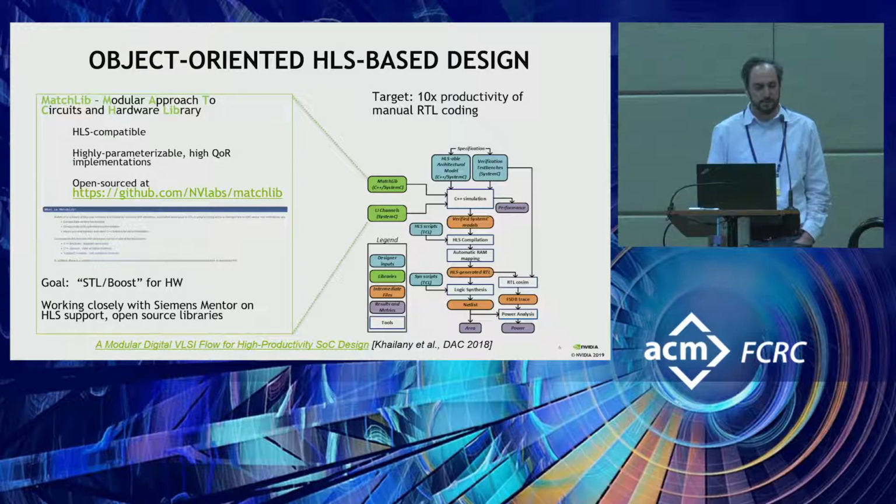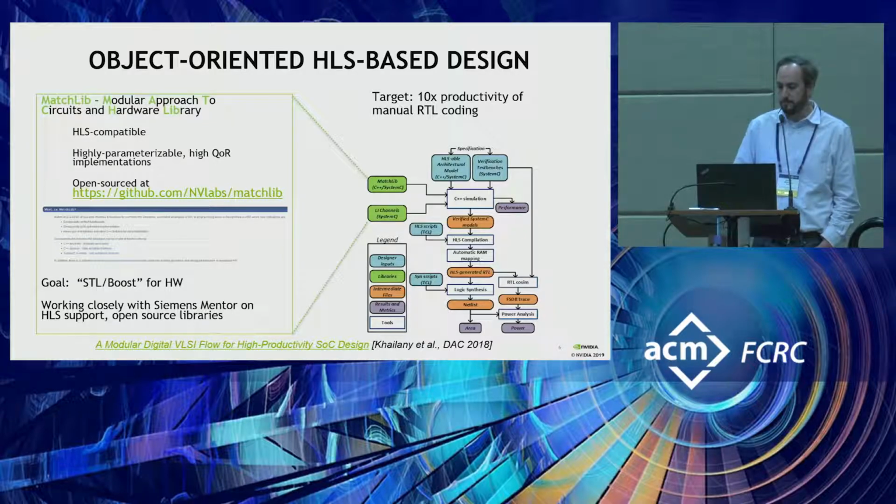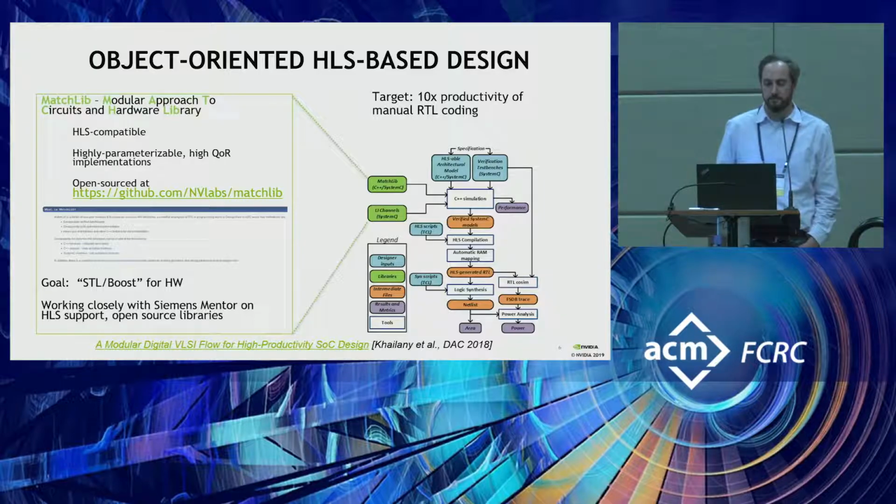Okay, so let me start with the first one, which is raising the level of hardware design abstraction. The approach that we've been pursuing, we're calling object-oriented HLS-based design. So we're using a high-level synthesis tool as our compiler. But rather than directly compiling application code to gates, or to RTL, I should say, we're essentially trying to raise the level of abstraction that hardware designers code in, similar to Chisel and other efforts.